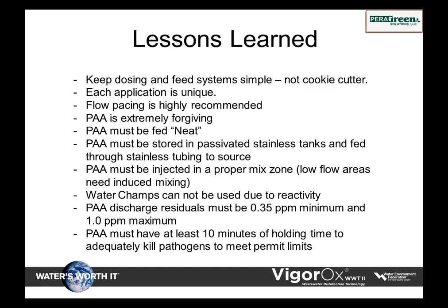Now, I'm going to close it up here. You can see that the way we approach it is from a complete plant perspective. You've got to keep the dosing and feed systems simple, not cookie cutter. What's interesting here is that I'm going to tell you a little story about Steubenville. I think everyone's experienced some cold weather lately. Well, about 3 weeks ago, they had real cold weather. They got ice on their sonic flow meters on the discharges, and they weren't usable. So now they didn't know how to flow pace.